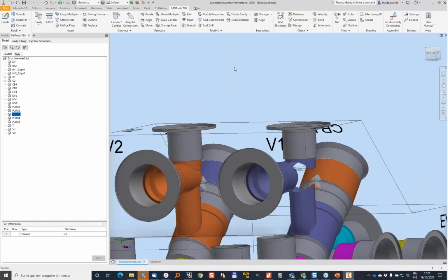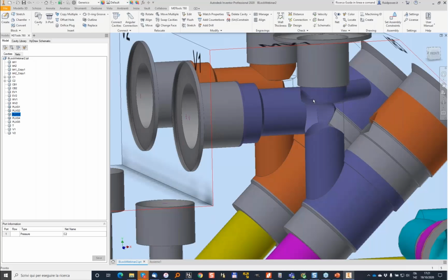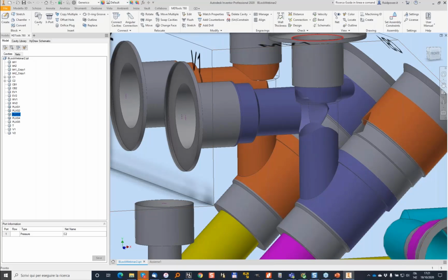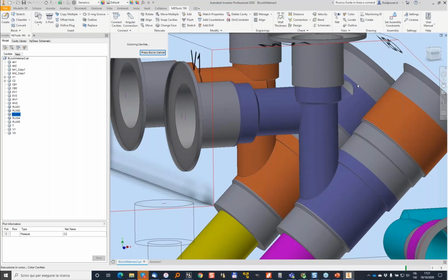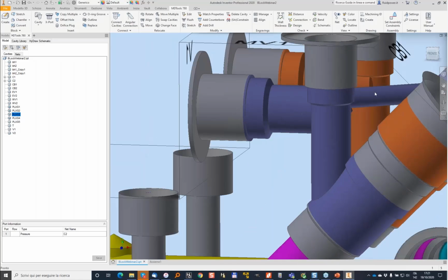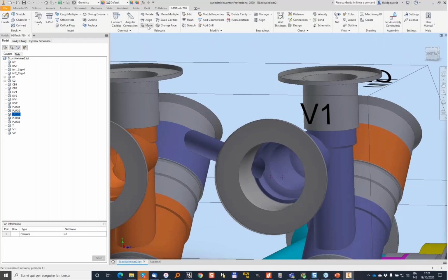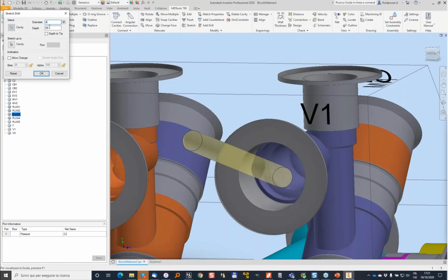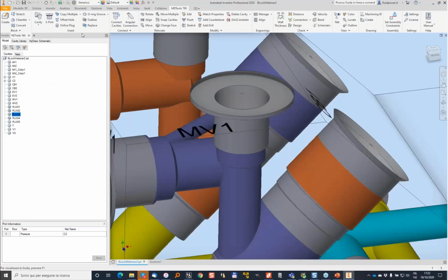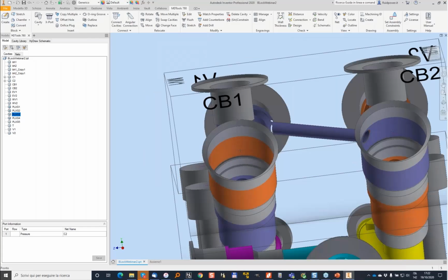And that's our connection. When you see graphical artifacts, like in this case, you just need to click color, and MDTools will recolor all the block and render properly all the cavities. As you see, we did this connection, which is fine. Let us make it 4 millimeter and make it 75 deep, so that we have our connection.